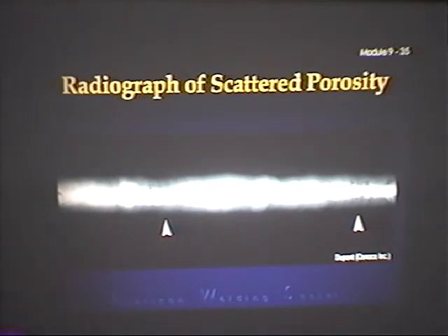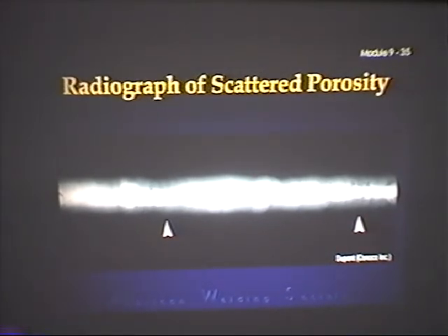Remember, those of you that are into pipe welding, I tell you to stagger your starts and stops. The reason is, if you have some porosity or trapped slag or something, and you spread it over a wide distance, it may be acceptable by code. But if you have all your starts and stops in the same spot, it concentrates those discontinuities.